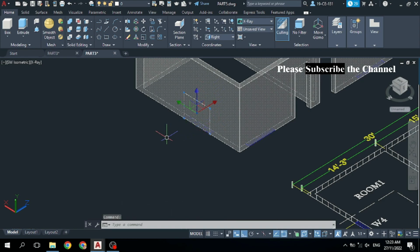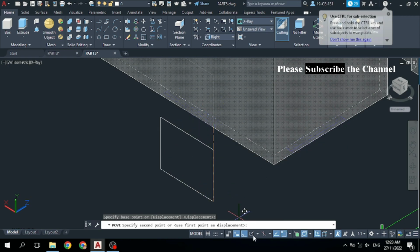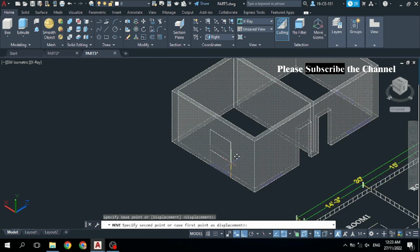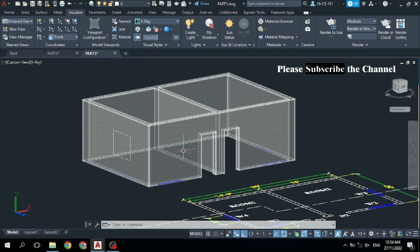After that you know that our window is upward, so click on it and then right click and Move and specify this down point as your base point, and Object Snap must be on, and then go upward by the distance, let's say 3 feet upward, so type 3 feet and press enter. Now you can see this rectangle is 3 feet upward.